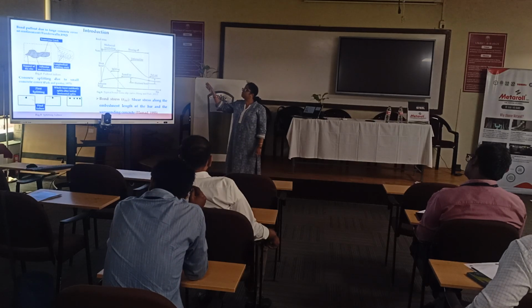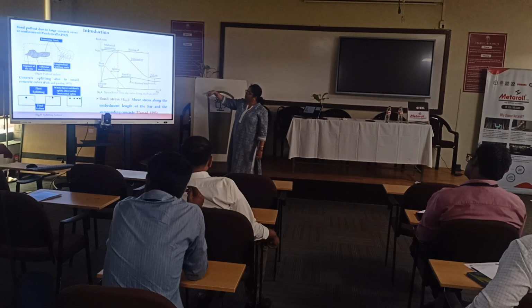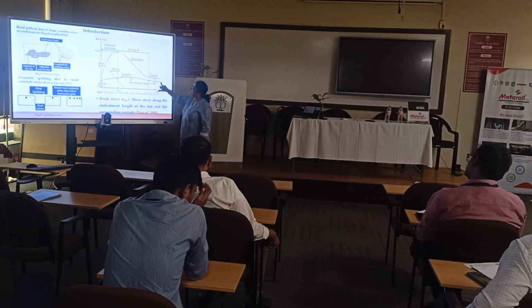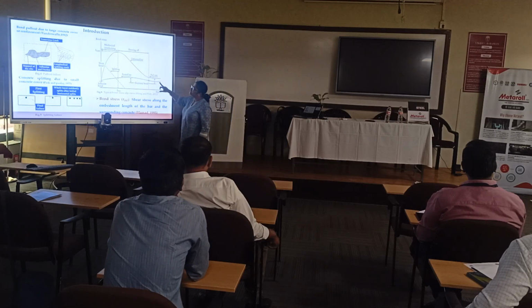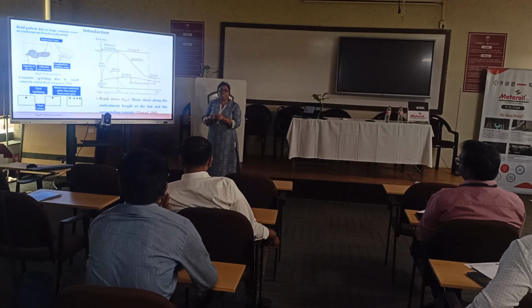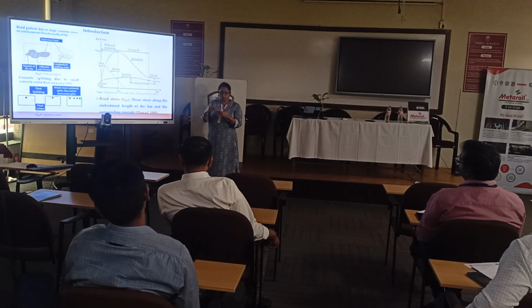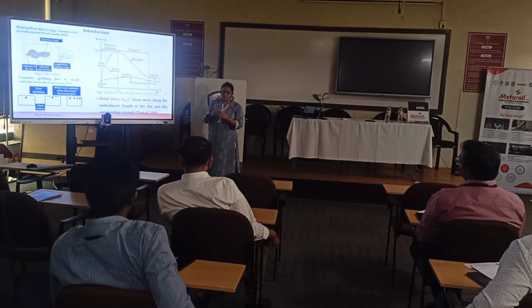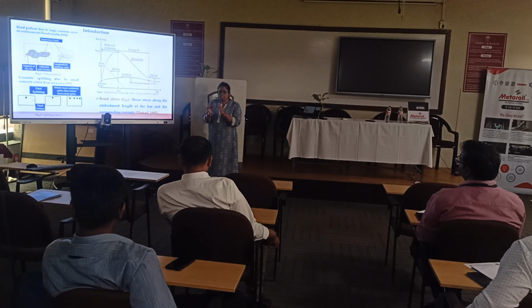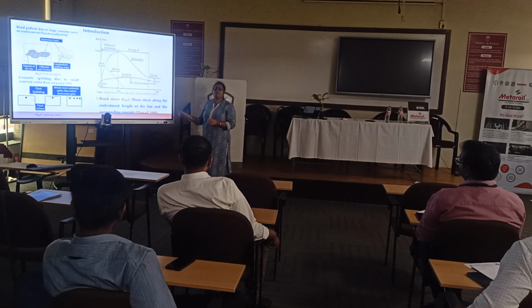This deformation is always noticed in terms of higher maximum stress and a longer slip. Slip means the relative deformation measured from steel to concrete. The steel has to be deformed and the surrounding concrete also crushed, so the relative displacement is measured as slip. The larger the slip, the better the resistance to bond failure.